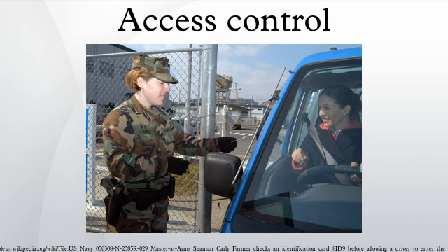Communication with the controllers may be done at the full network speed, which is important if transferring a lot of data. In case of an alarm, controllers may initiate connection to the host PC. This ability is important in large systems, because it serves to reduce network traffic caused by unnecessary polling.